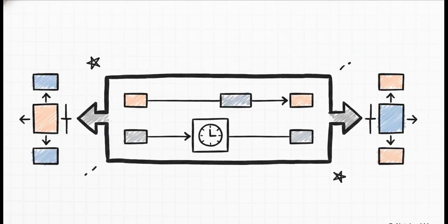Think of Verilog's syntax as your actual engineering tool belt. Defining modules and ports sets your hardware boundaries, while choosing between a wire and a reg data type dictates how the data physically moves around. You're going to use continuous assignments to build out those instant combinational paths, and procedural blocks, like your always blocks, to really breathe life into your sequential logic. Oh, and to make sure that code is scalable, you'll leverage parameters and generate blocks.